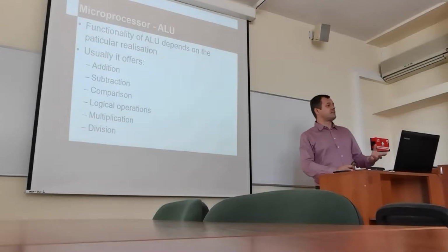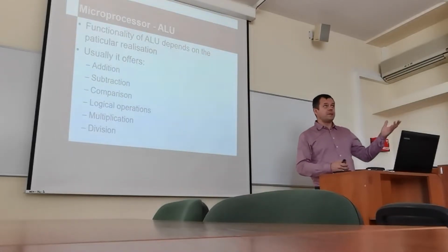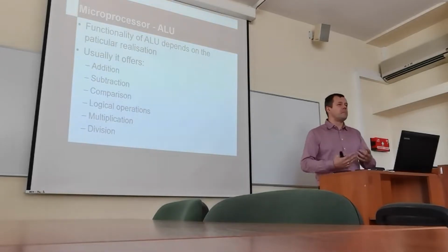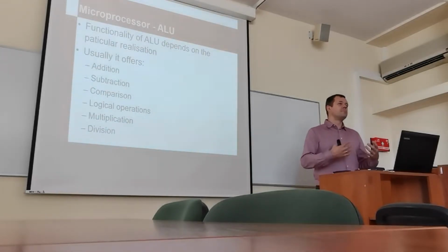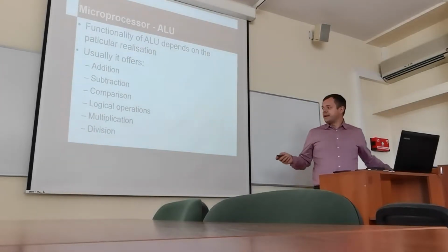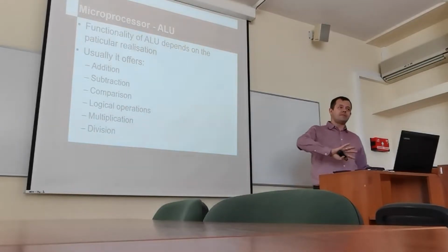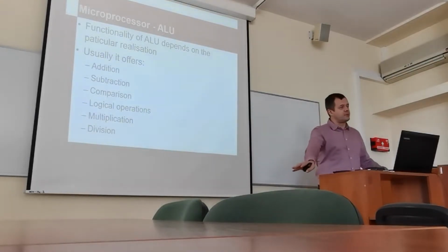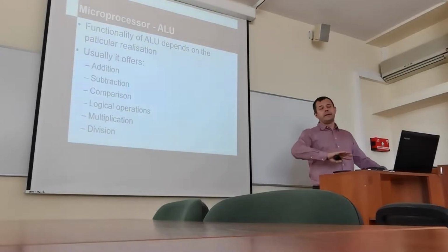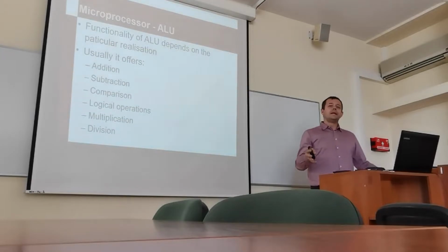But for multiplication, it's theoretically possible to make a single-cycle multiplication, but that requires a horrible amount of logic, of components. That's why, to make everything simple and concise, quite often the multiplication and division are delivered by a separate processor, we call it, a separate module which is used just for calculation of multiplication or just for calculation of division.